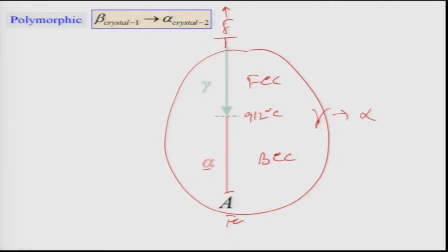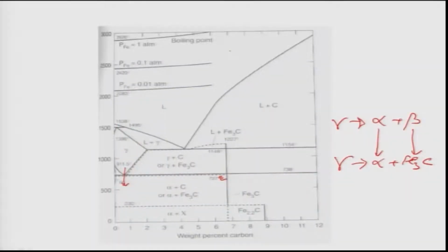The moment we add carbon into it, things change. That is what is shown in this phase diagram. As you add carbon, the transformation which was happening from alpha to gamma at 912 degrees Celsius decreases. That is what is shown by this line. This curve is telling you that the transformation temperature of gamma to alpha, or alpha to gamma, is a strong function of the carbon concentration in the alloy. It decreases very rapidly to about 0.77 weight percent carbon, where there is a dip, a lowest minimum position, and at this temperature there is a horizontal line as you see here.